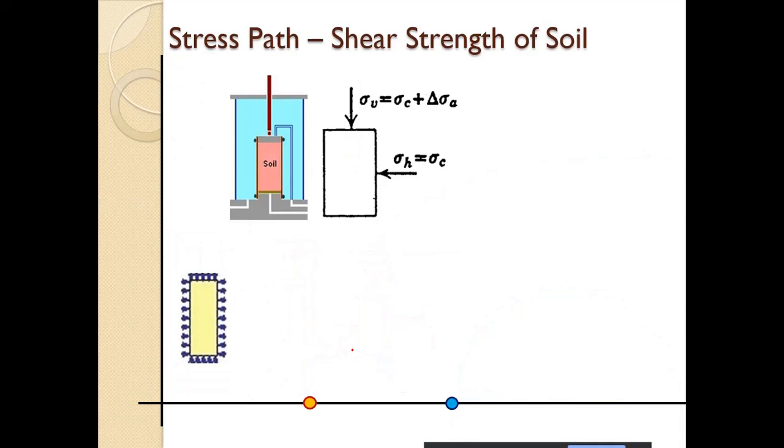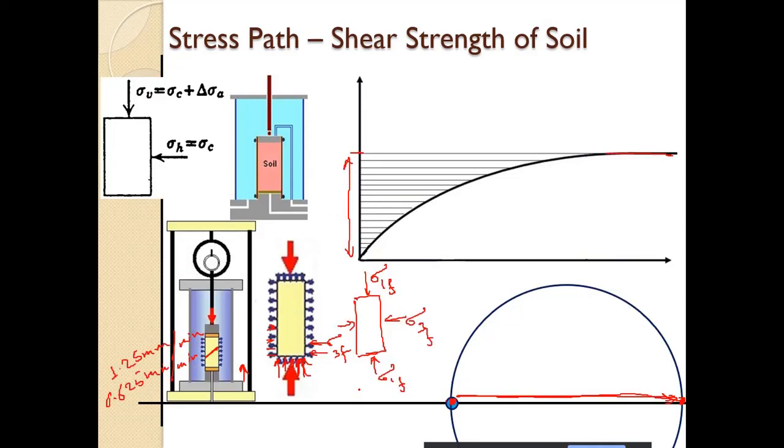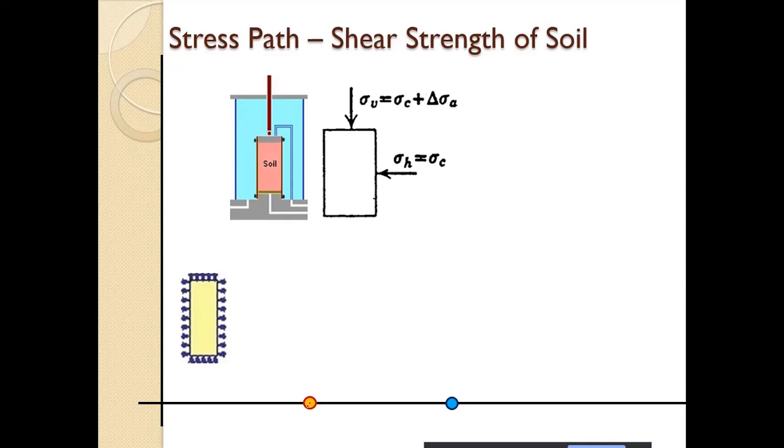Okay, so now we concentrate on the effective stress state. We have initially seen that this is the pore water pressure. What we are going to do is shear the sample in a drained state, so drained shearing we are going to do for now. And we are going to maintain this pore water pressure as a hydrostatic pore water pressure.